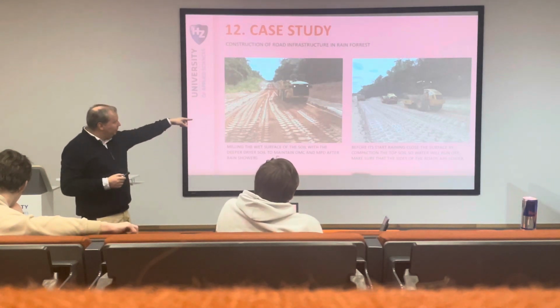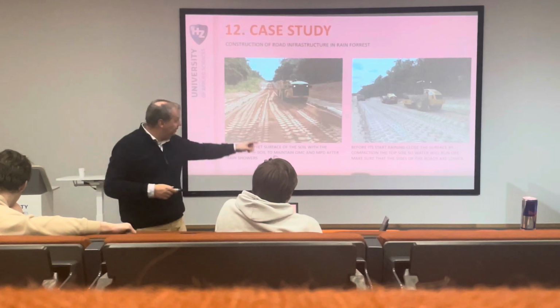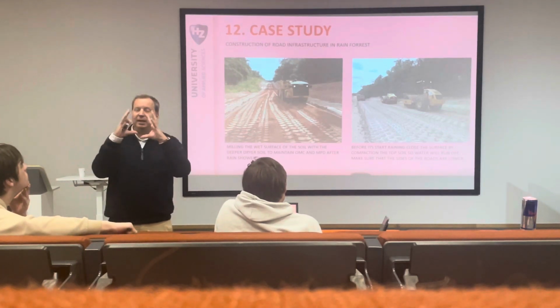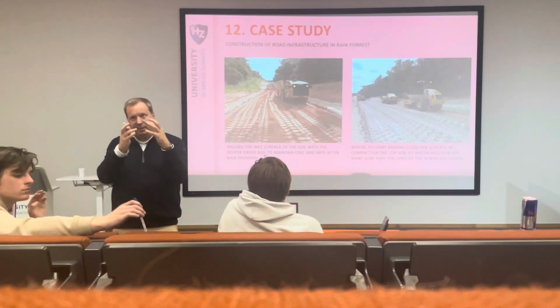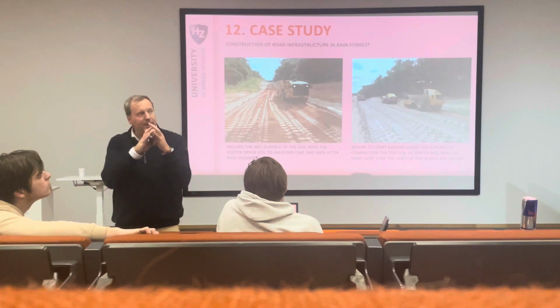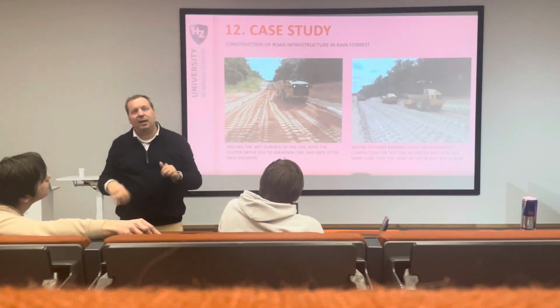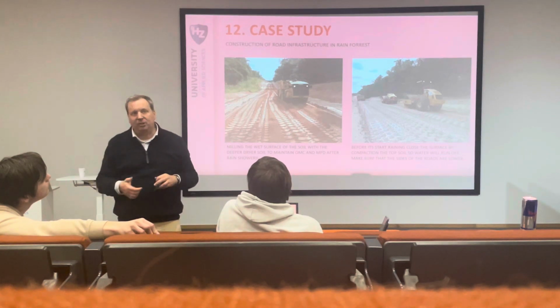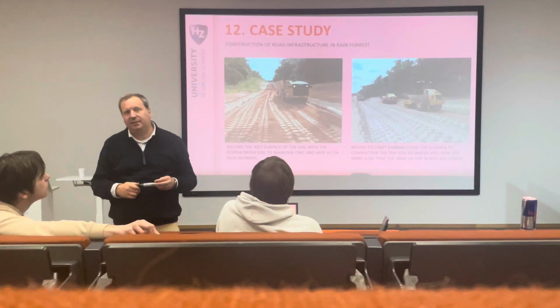There you can see that we use a sheep foot compactor. When you have clay, there are some lumps, some big fat clay parts. By using a sheep foot compactor, you basically squeeze the cement, the product and the water through those lumps. So we use it not only for compaction but also to mix it better.